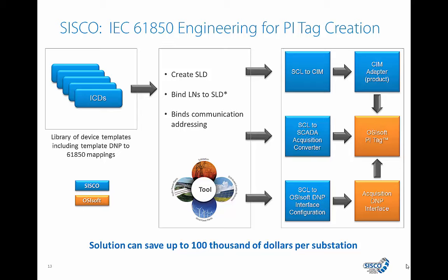These IED configuration description files, ICDs, can then be imported into a substation engineering tool. A single line diagram can be created. It can bind the measurements to topological elements in the single line diagram. And it can bind communication information to the instantiated IEDs.